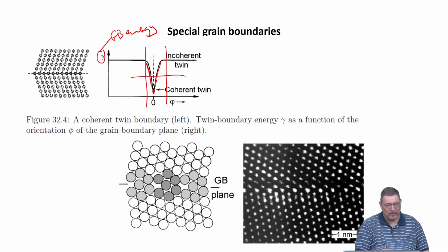And then also it depends on the stacking fault energy of the material, because in general the twin boundary energy is related to the stacking fault energy. And this can be very different for different materials, right? So there can be almost 2 orders of magnitude, 1.5 orders of magnitude variation between the stacking fault energies of different materials. And so that all affects how an annealing treatment would serve to get more coherent twin boundaries. But in all materials, the general direction would be if you anneal, you get more coherent boundaries.